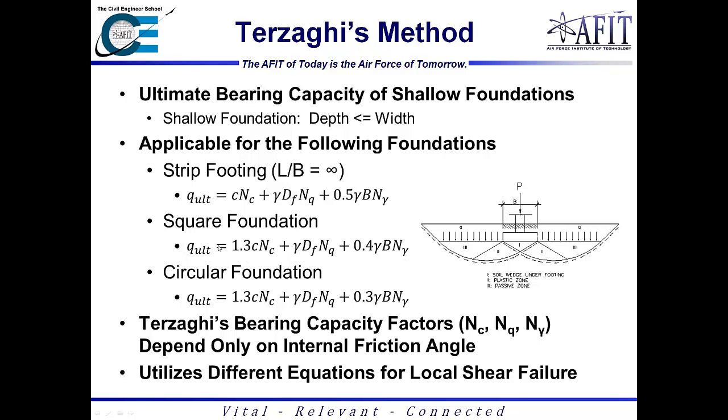And so Terzaghi's bearing capacity factors depend on the internal friction angle. And on the next slide, I'll show you what they actually look like. However, as I said earlier, this applies to the general shear failure mode. If you want to calculate for the local shear failure, Terzaghi has some modified bearing capacity factors that you can use to actually calculate it.